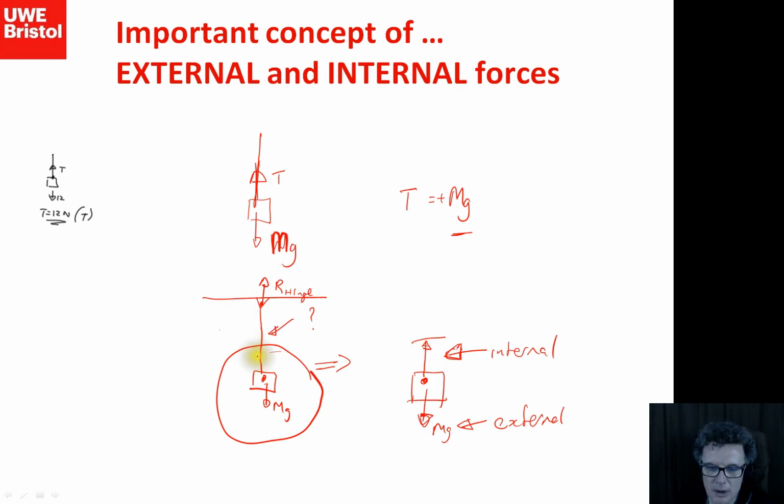So what else do we have going on in the string? So we've got this internal force, and you could say just outside of that cut that I've done, there's another internal force which is balancing. So all the way along the string I can make cuts, and then either side of my cut I'm going to have this tension all balancing all the way through the string, equal and opposite, so they don't add to any sort of resultant force.